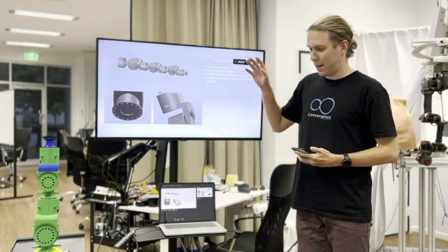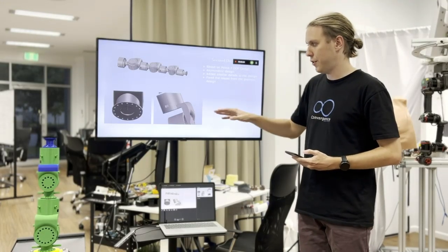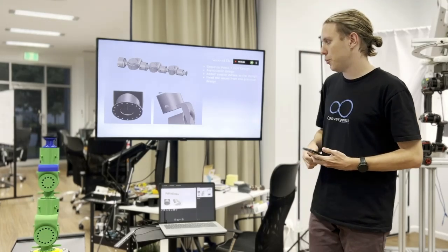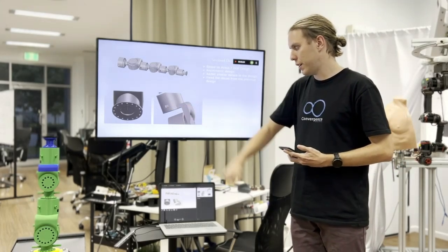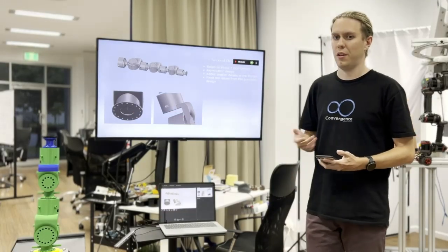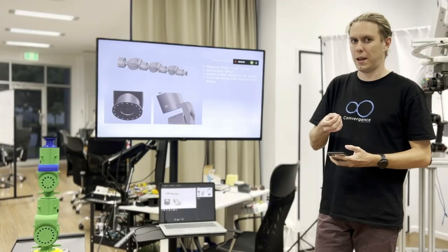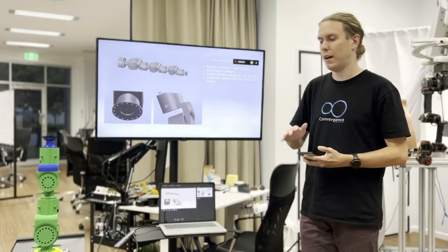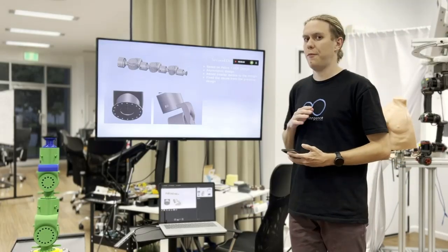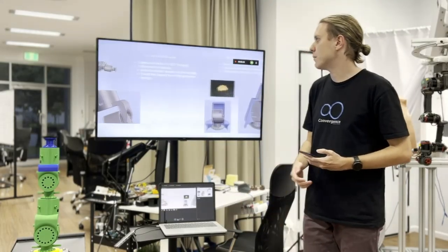So I also added smaller details to the design of this 7 degree of freedom robot. Some of the things were the wiring holes, which you can see here, and the indents on the bottom of the motors, as the motor actually has a little bit of extra space underneath, so it's not completely flat. So I had to rectify that, and it fixed pretty much every other issue in the previous design.